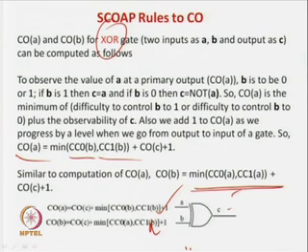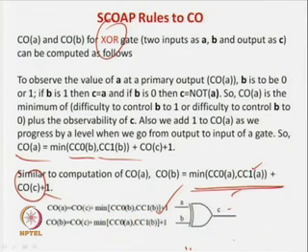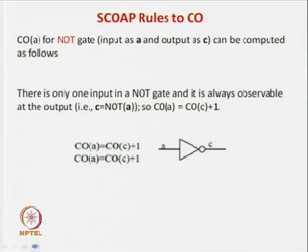Okay. Why? Because if you want to propagate B, so if A is easier to control to 0, make A equal to 0. If 1 is easier to get at A, make it CC1 of A. So, this is the case, and 1 for the level jump, and it is observable via C. So, make this one and this one. So, there is a slight mistake. So, this one will also be A, correct. So, this is how we go for the computation for an XOR gate.